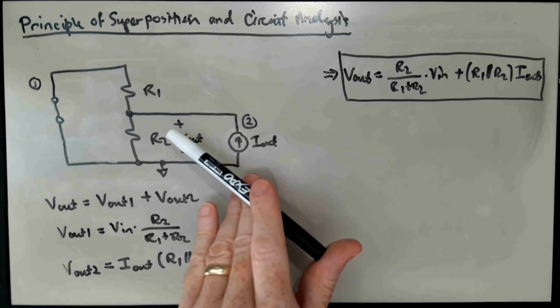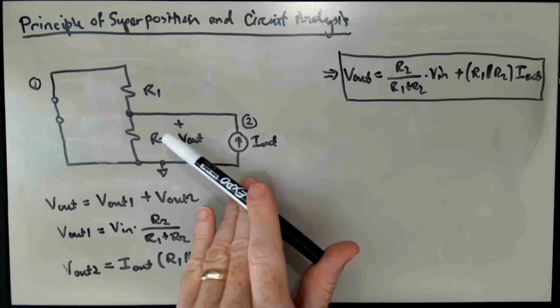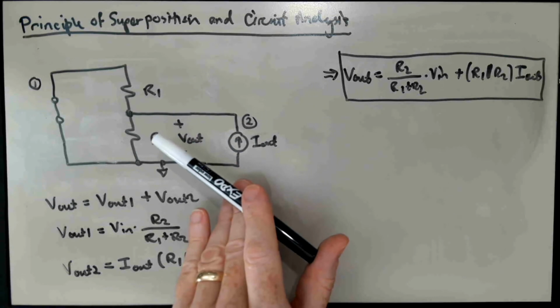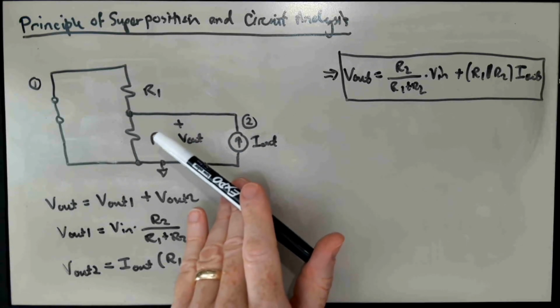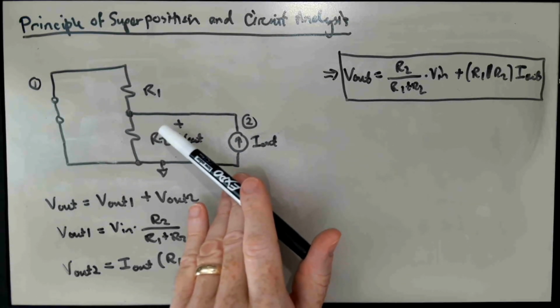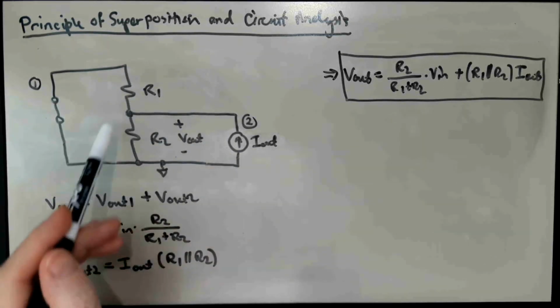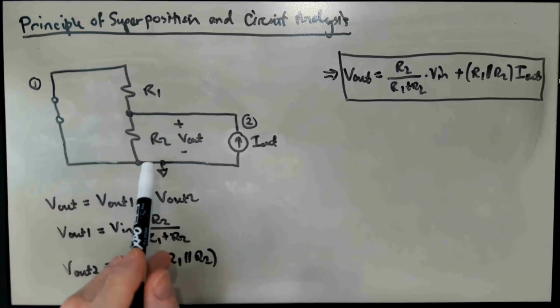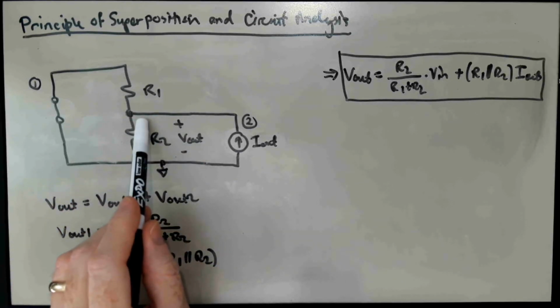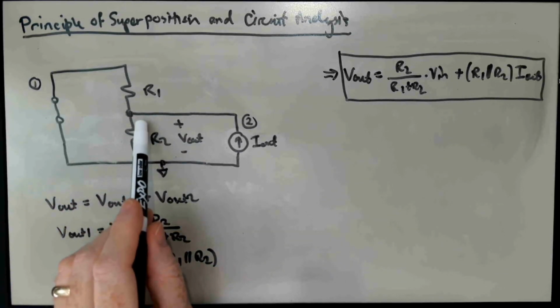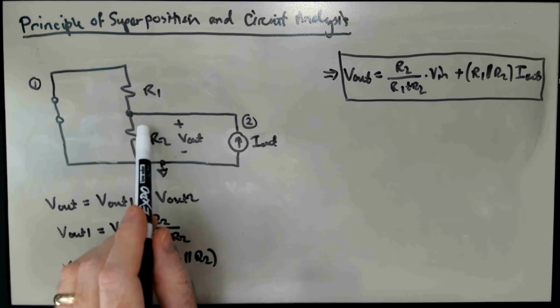Because kilo times milli is basically 1, right? 10 to the third times 10 to the minus third is something on the order of 1. And so if I'm pulling out milliamps of current and I've got kilo-ohms of resistance here, that means I'm shifting this voltage away from its desired value by volts, which is quite a lot.